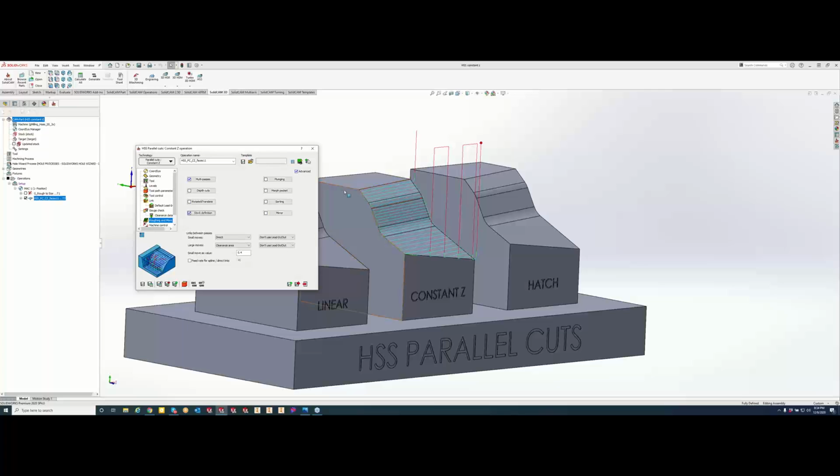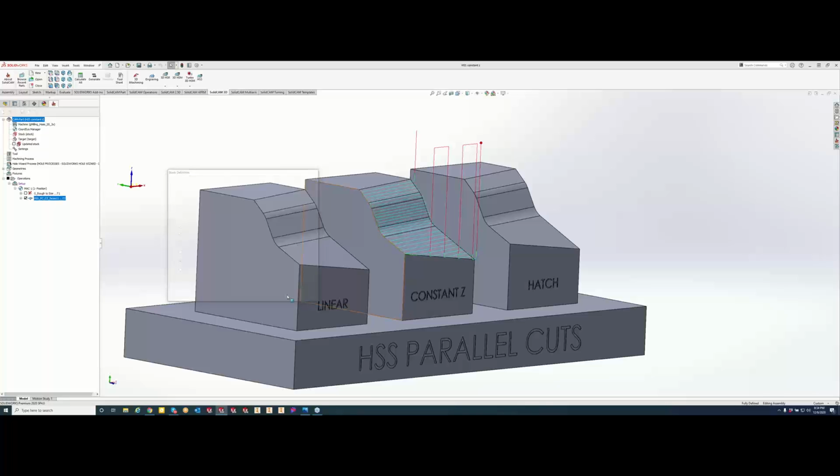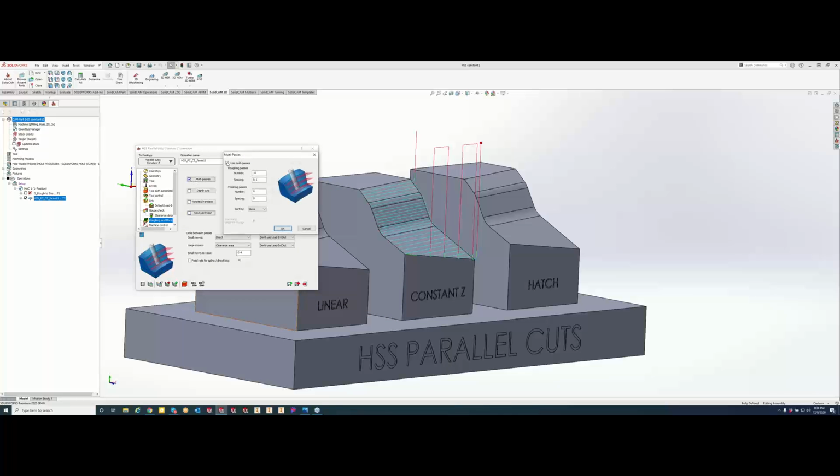So now we're telling it to trim it, so we're not doing any air cutting in there. And as well as our links between passes for that area right there. So we can see we do have some jump ups in there. So let's go ahead and turn that off. And multi-passes, we'll turn that off.